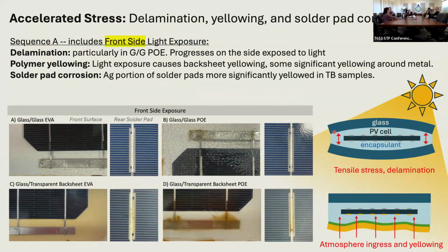So they're not very big mini modules. For glass full modules, I think for a large part the industry has fixed this by using the double heat press plate laminators, and they don't use the bladder laminators that would pull down on the edges as much. So that hopefully is fixed just with the instrumentation, and also just the extent of how big the modules are. It wouldn't be as big of a surface area effect, I guess.